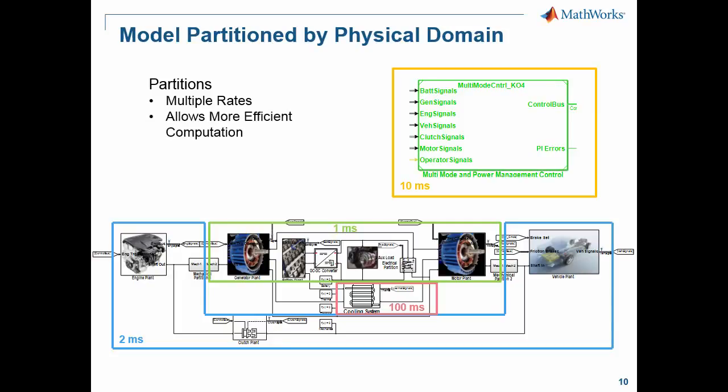Partitioning the model allows for more efficient computation and makes it much more scalable for use with real-time hardware. For example, we worked with DSpace and implemented the partitions exactly as shown, where each partition ran on its own processor in a hardware-in-loop environment.